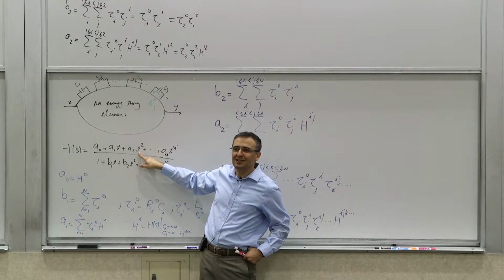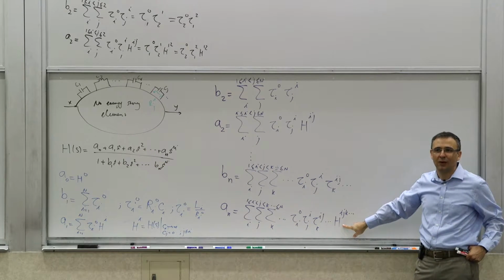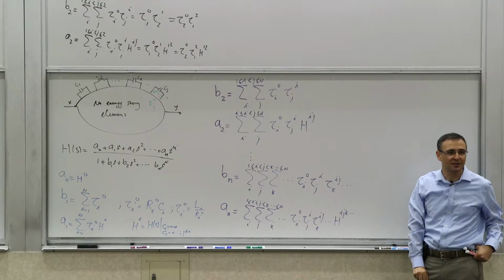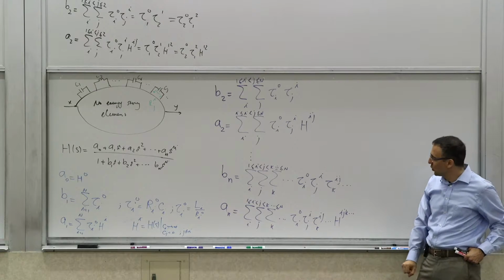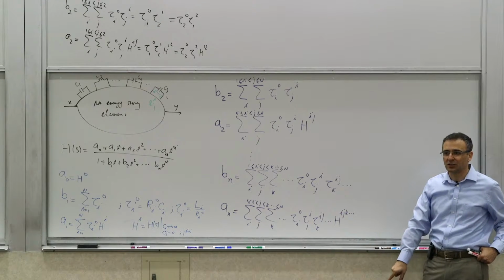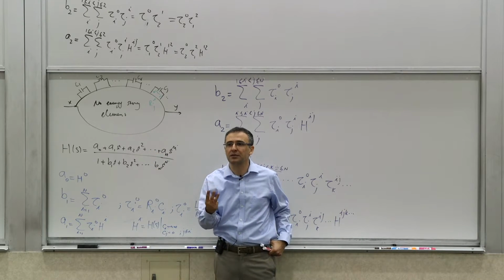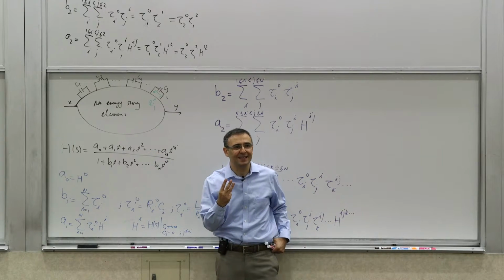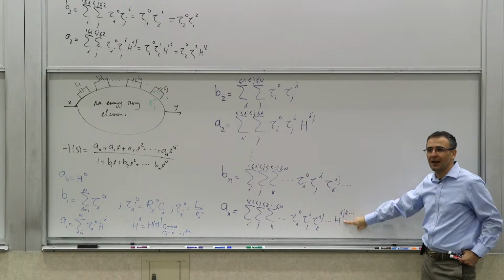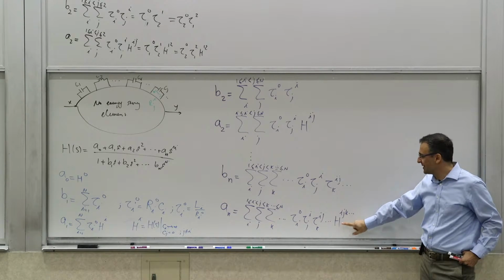So to get a non-zero A coefficient, that transfer constant of that order, at least one of the transfer constants of that order has to be non-zero, right? So if you have a third order, let's say H1, 2, 3, that's non-zero, it means that you will have a third order term in the numerator, which means that you have 3 zeros. That's why the test is the maximum number of elements that can be simultaneously infinite valued and produce a non-zero transfer constant. So this is where that test comes from.